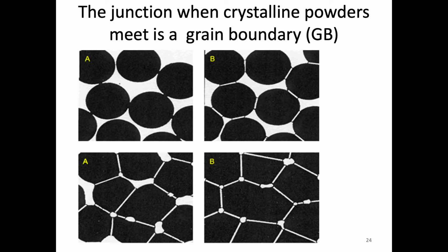Okay, so we start out before sintering with kind of the structure you see here in A. This is where we just have powder particles. Each one of these is a crystalline powder particle. And they're basically, again, just held together either with the binder or with van der Waals forces. So they're really not held together. And so if you touch or try to handle this part, it tends to break apart.